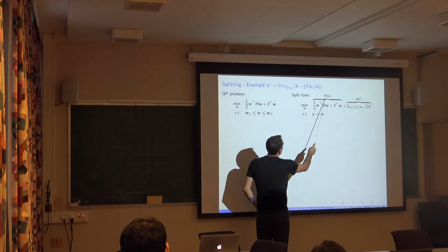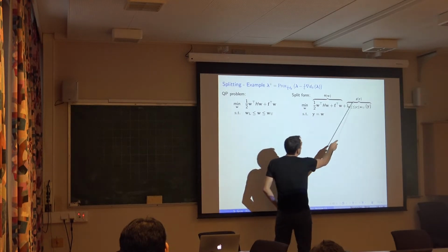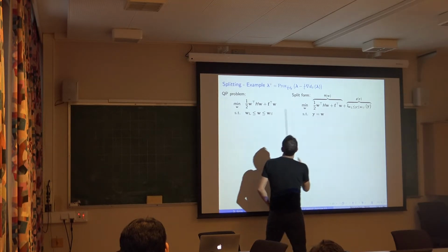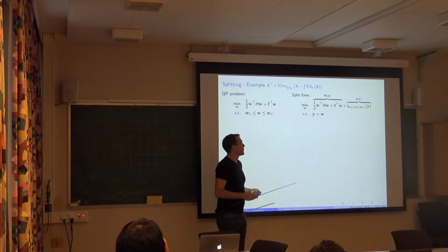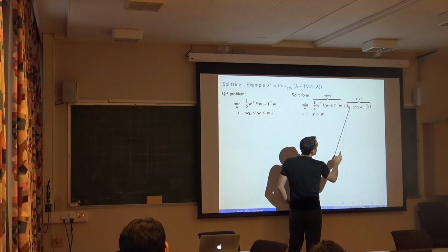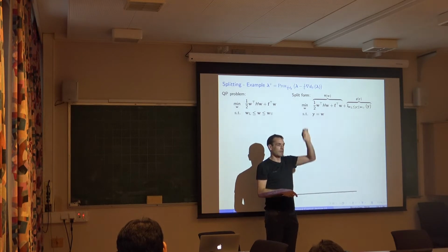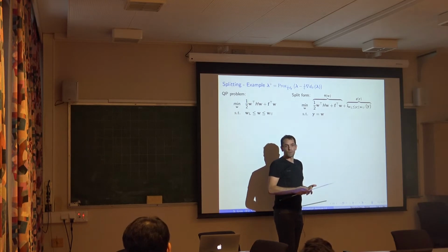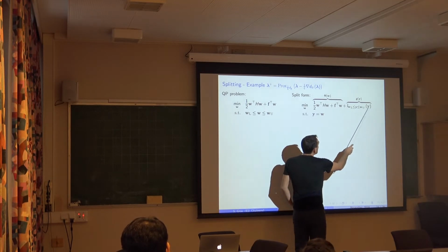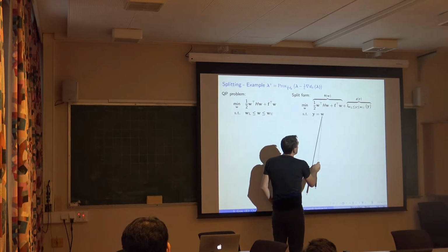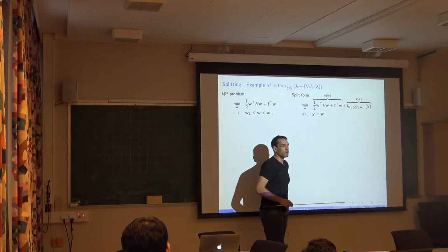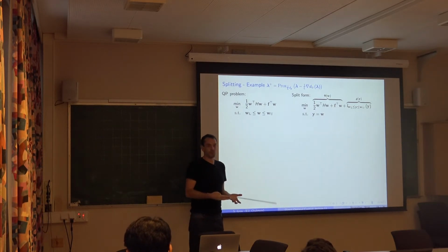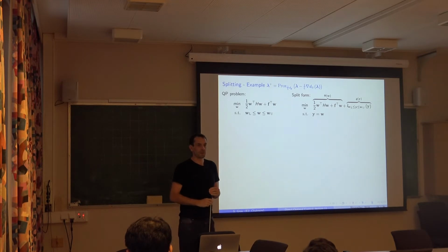You call it phi of w. And then you create this indicator function that becomes infinity when y leaves these bounds, right? So that's this I of this guy here. That's one way of noting a function that takes infinite values when the constraints are not satisfied, and that takes 0 value otherwise, evaluated on y. And then you basically make a copy. You say y should be w, okay? So that's one way of putting this MPC problem in this splitting form. Does it make sense?